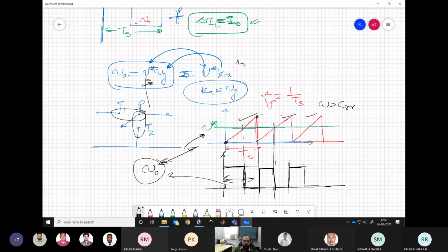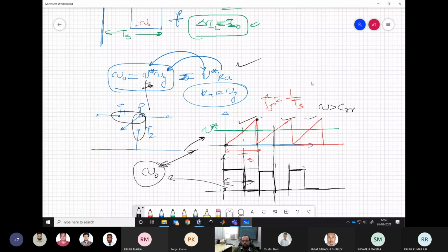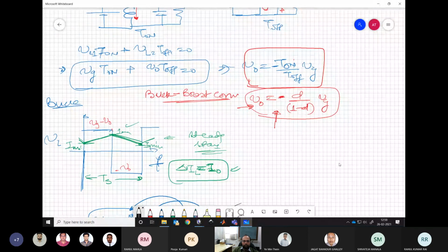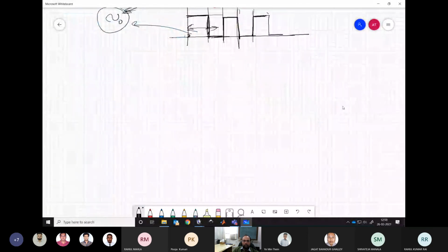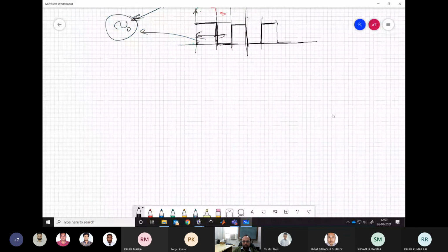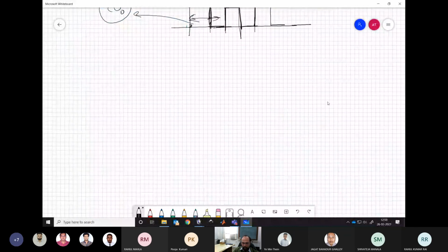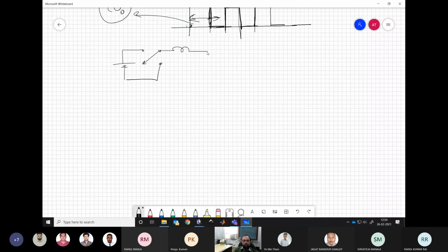So then we have realized in a generic form how our power converter should be. In case of DC motors, let us say separately excited or any other excited DC motor, if we talk about a buck converter, we may ignore the capacitor branch over here.